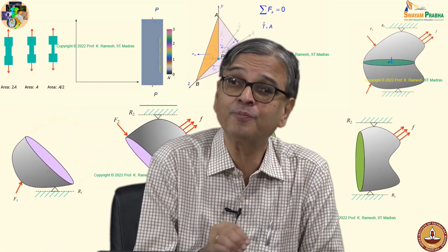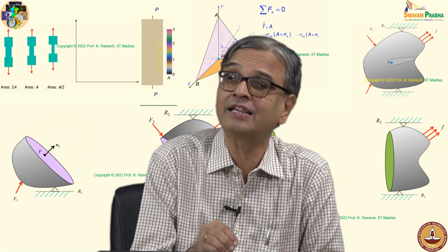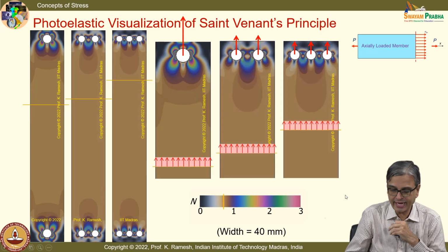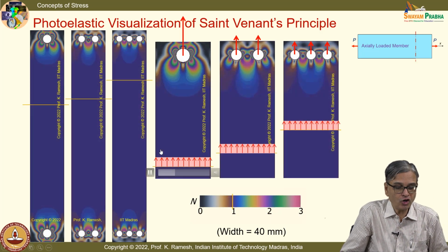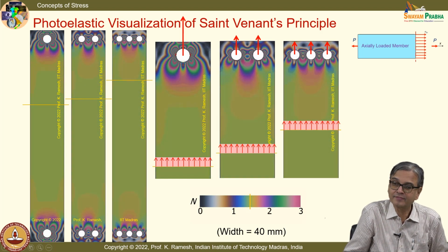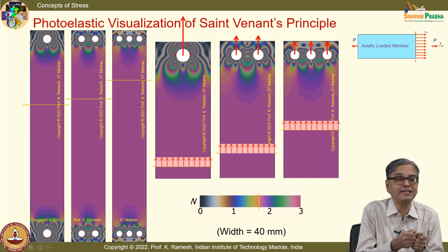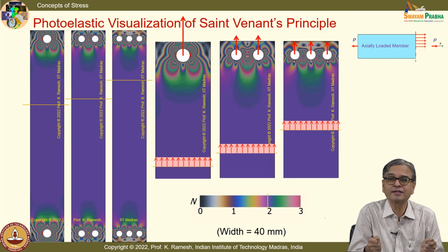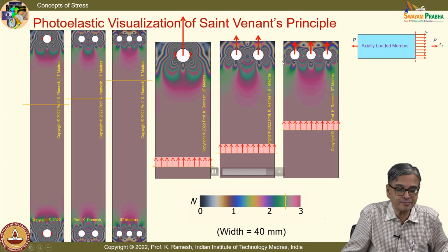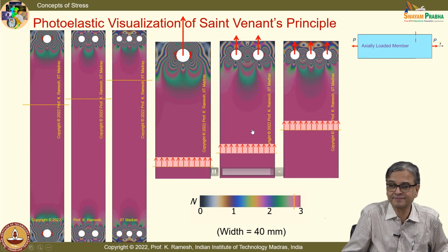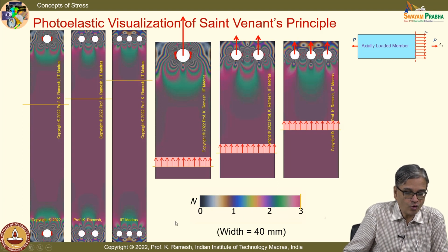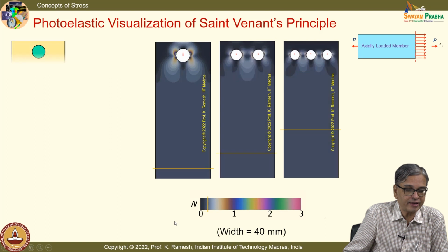In fact, none of the books give you a pictorial representation in a manner that is represented here. Okay. See, the idea is to have a uniform pull is what we want. And what you find is, by the way that you apply the load, there are local disturbances, and these local disturbances die down after a distance. Fine. And this goes by the principle called Saint Venant's principle.